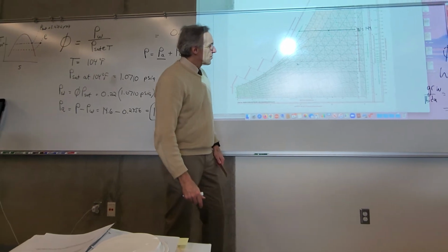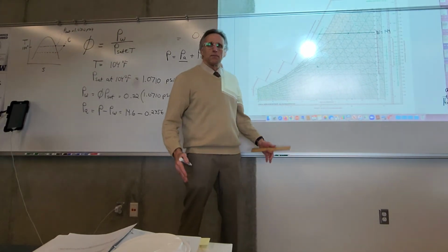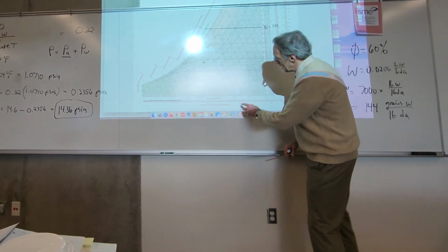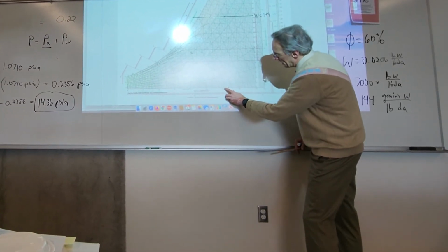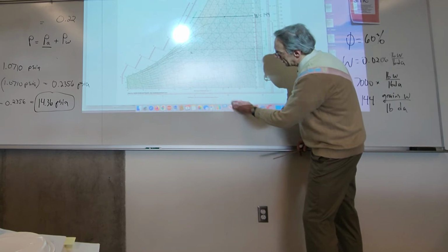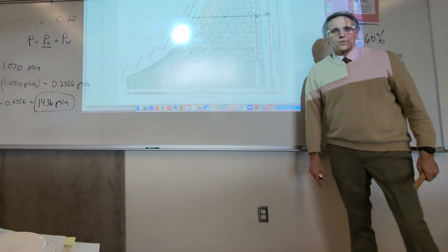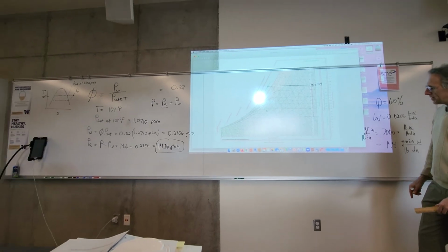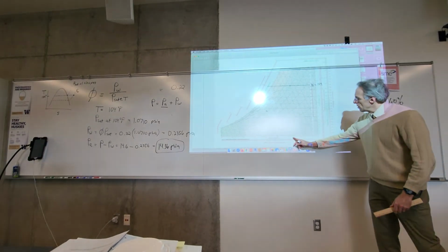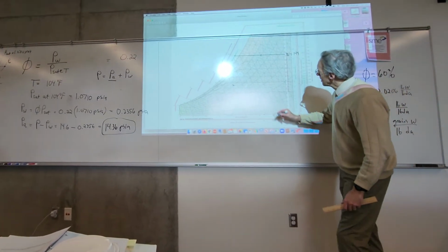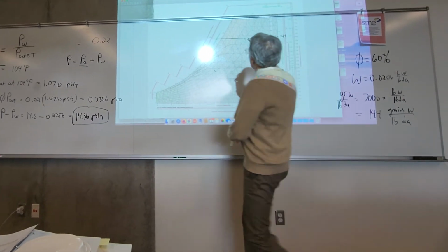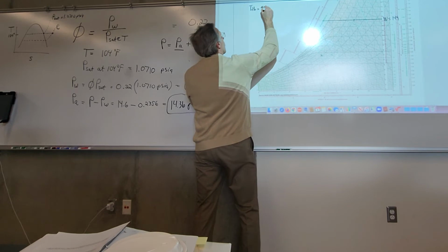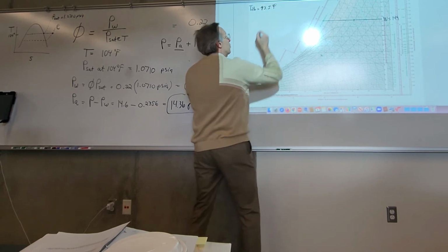I think to the 10th place is fine. It's hard to get to a finer grain than 90, 90.5, 91, 91.5, 92. I suppose you could split hairs if you're really careful and get to a 90.2, but 91, 92, 93.5 is good enough for 10th place. So dry bulb is 93.5 degrees F.